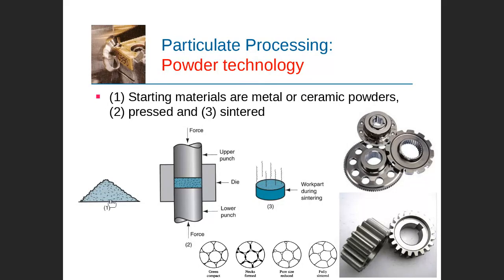We bring the powder. What powder? Metal powder. What metal powder? Any material. Actually, not only metal. It could be metal powder, ceramic powder, or polymer powder. It could be a mix of metal and ceramic, metal and polymer, or ceramic, metal and polymer. It could be a mix of several metal materials, for example aluminium, magnesium, silicon, like an alloy, but with no melting. We're not going to melt actually. So this is a powder, material powder.